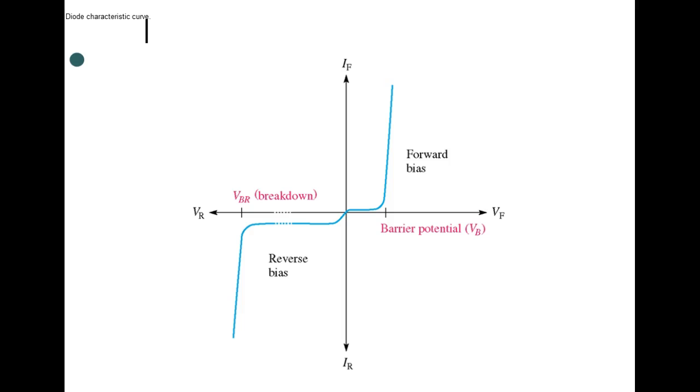So a diode is not an open switch, and a diode is not a closed switch. We say when it's forward bias, it acts like a closed switch, and reverse bias, it acts like an open switch, right? Well, in actuality, as soon as I put a forward bias voltage on the diode, we have a very, very small current leaking through it. And then what happens when it starts getting up to the barrier voltage, the barrier potential, it's going to start curving. It don't do this instantly. And then it's going to start going up. Once it's forward bias, then it'll actually go in a slope.